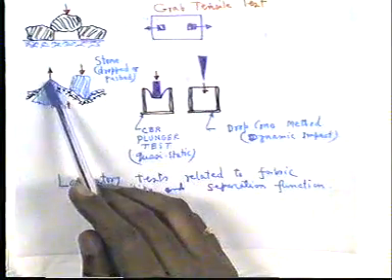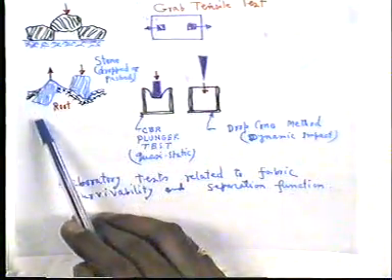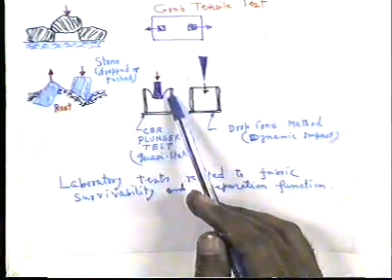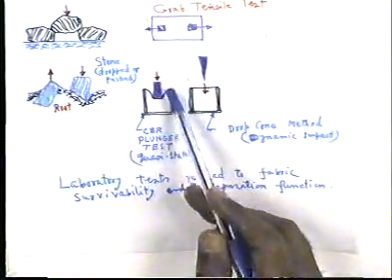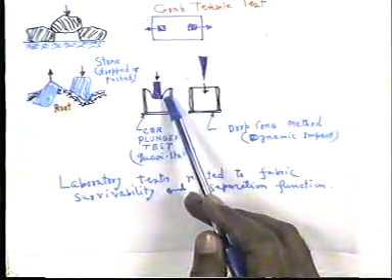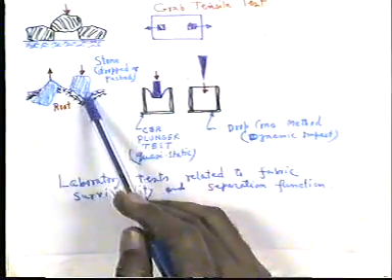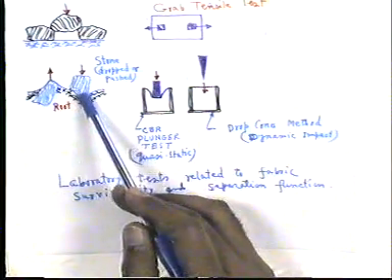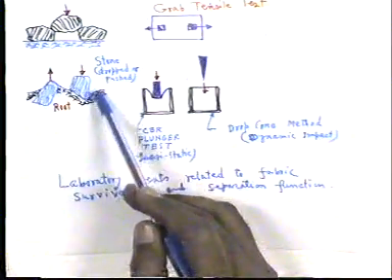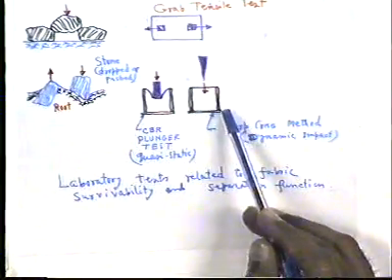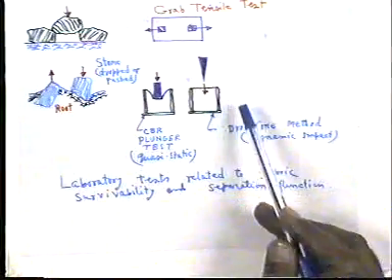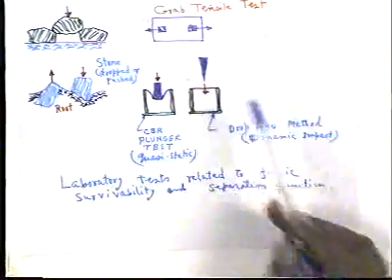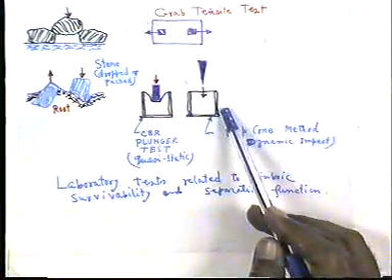When the aggregate is flat, we can conduct this CBR plunger test, which is also called the quasi-static test, or when the stone is angular and dropped on the geotextile material, we can conduct in the laboratory the drop cone method, or the dynamic impact.